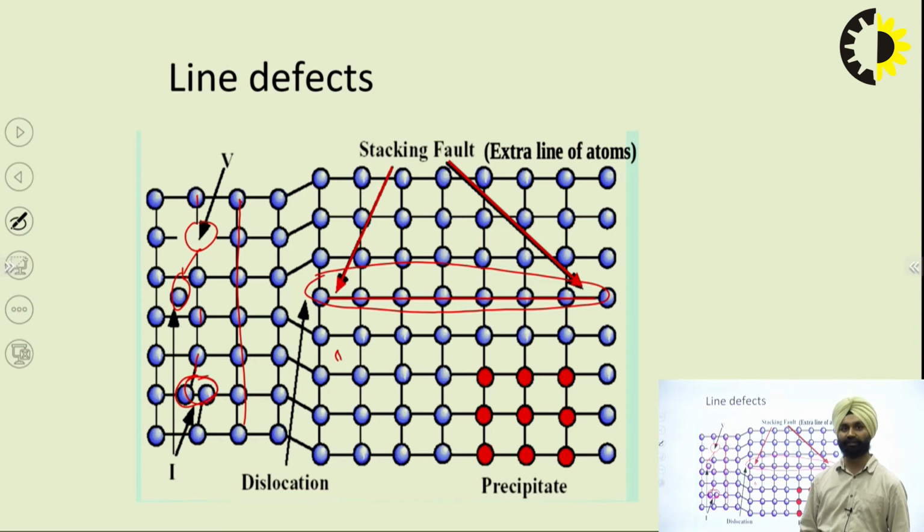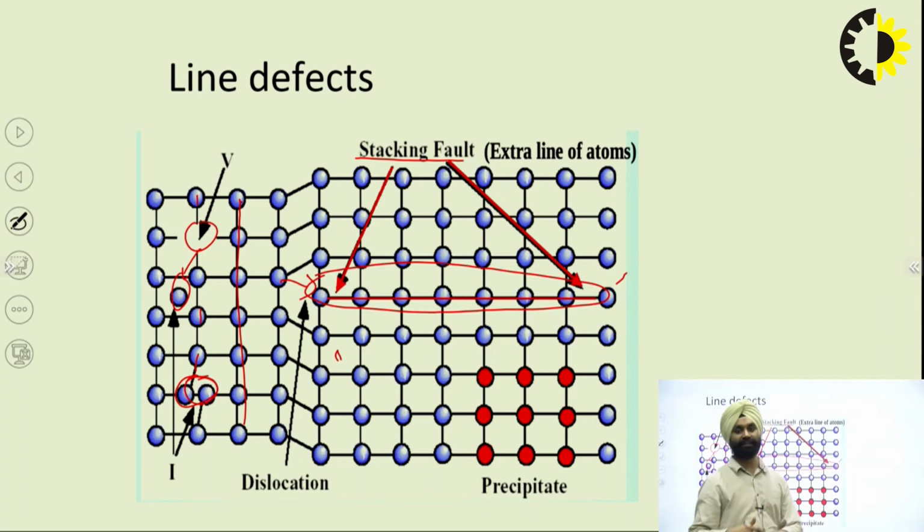This thermal stress will create this defect, which is another layer of the crystalline structure. This is known as the stacking fault. So a stacking fault is another fault where we are creating other stacks in the structure.